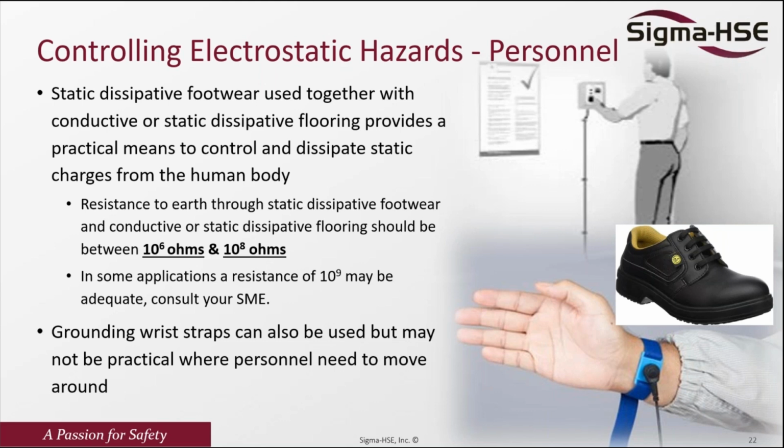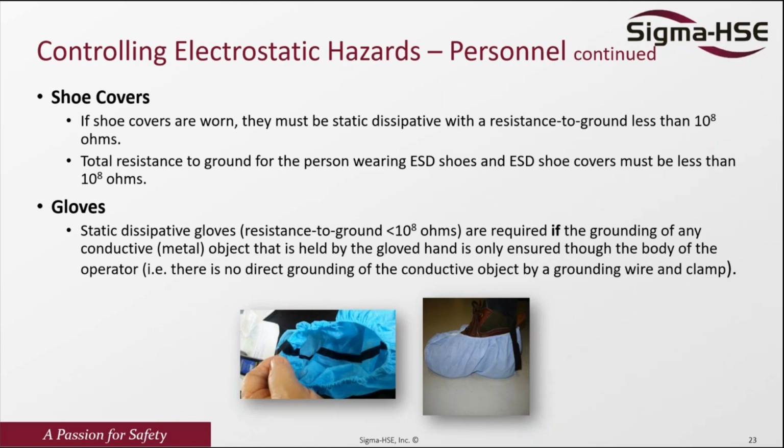That's why we always recommend that you have something to test it, to ensure that we actually measure between 10 exponent 6 to 10 exponent 8 ohms. And sometimes people have programmed it so that as soon as you attach it to yourself, it will turn green or red. That is very, very important. Sometimes we can use a shoe cover or gloves, which is very, very important.